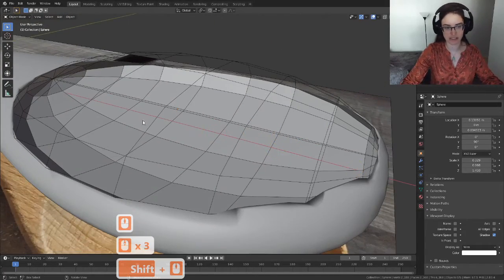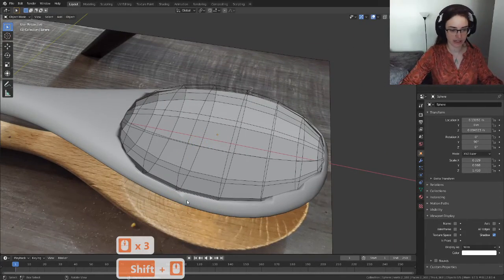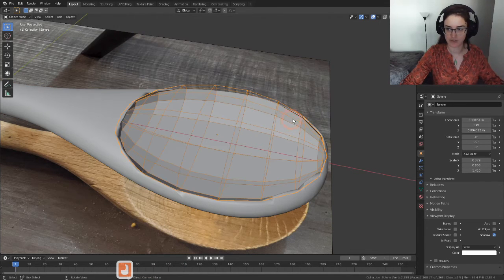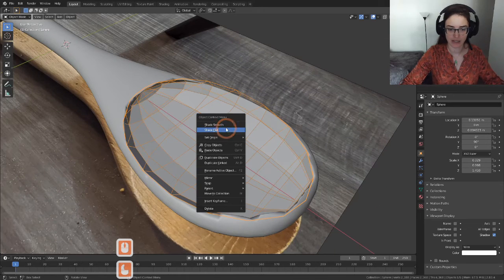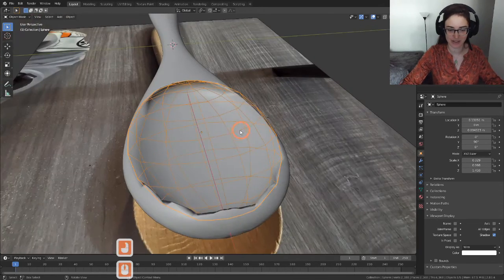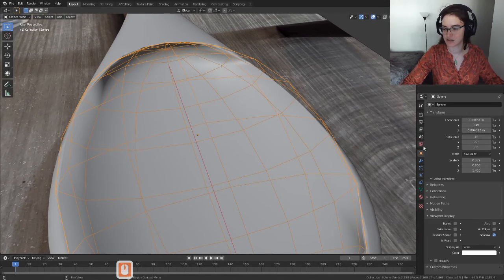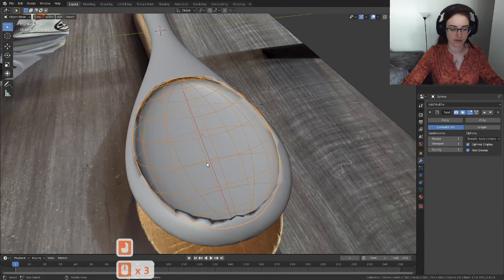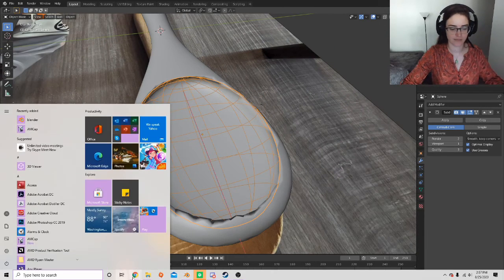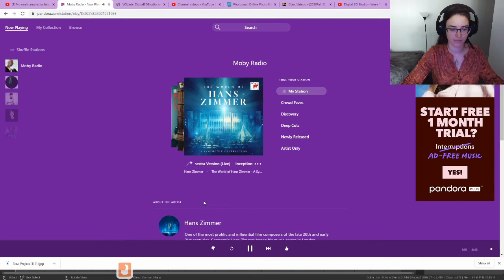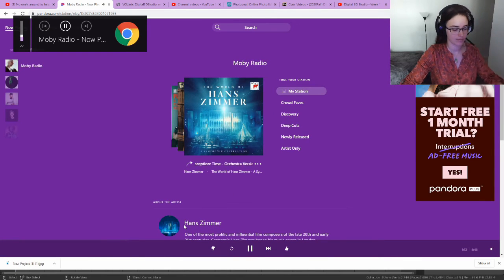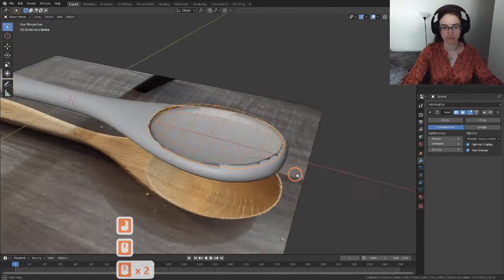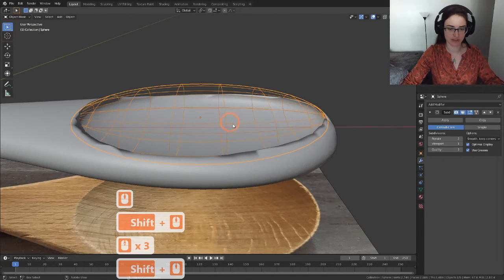And you can see it's really, really chunky right now. So we want to smooth out the sphere shape. So I can right click, hit smooth, and I might even want to add a subdivision surface. And now we can play around with the placement of this.